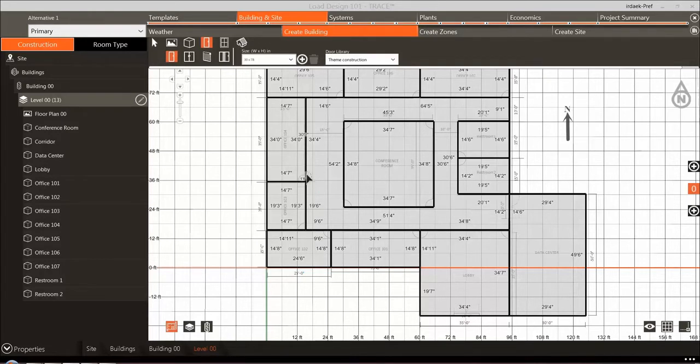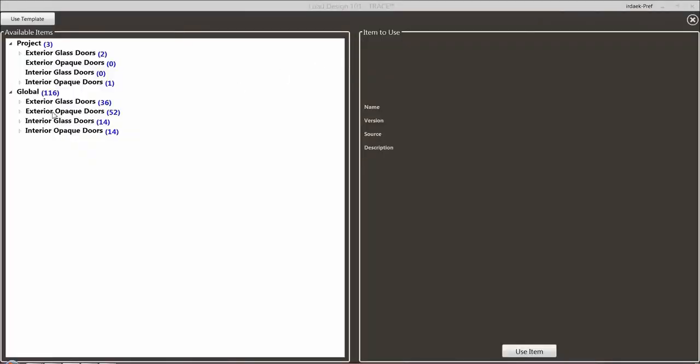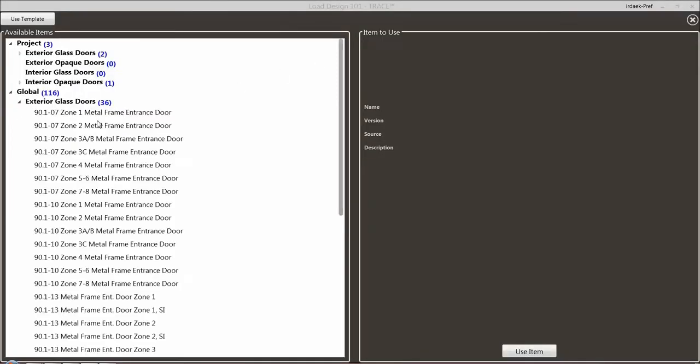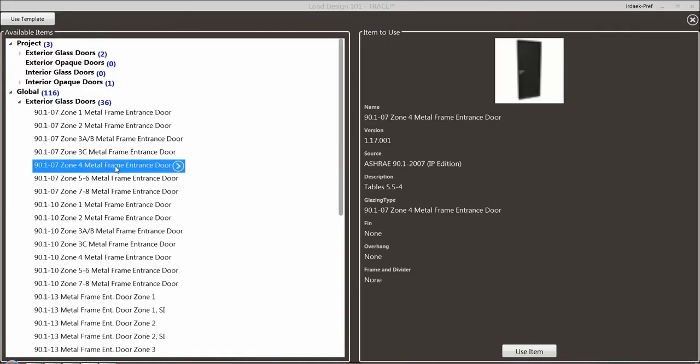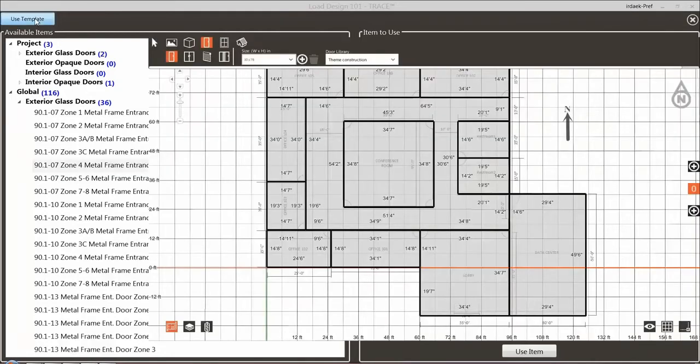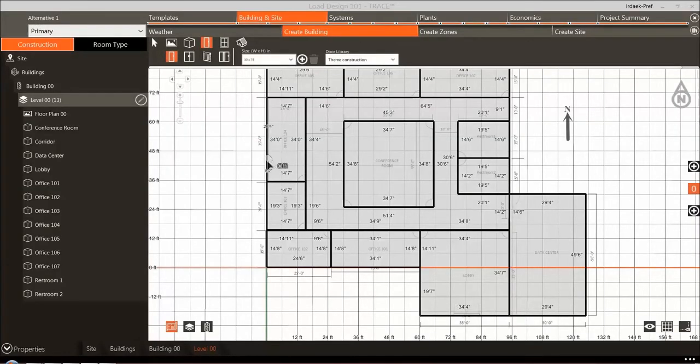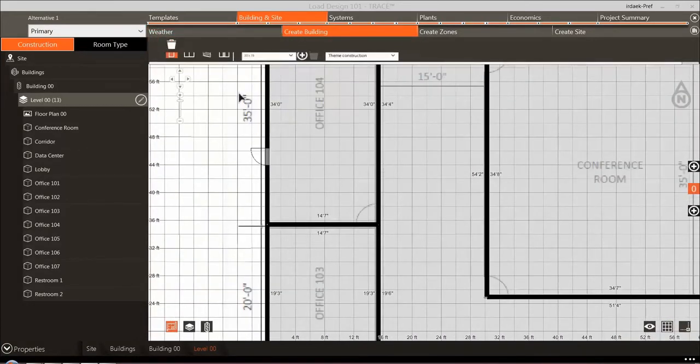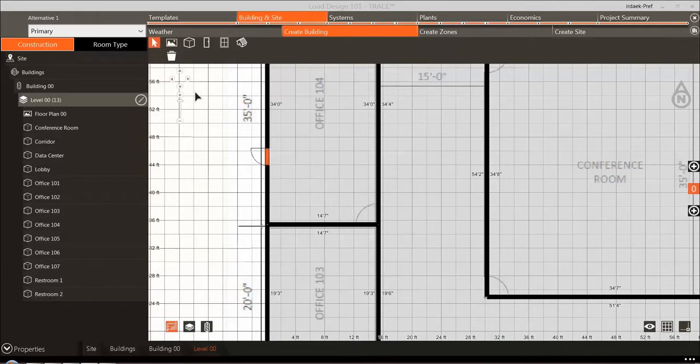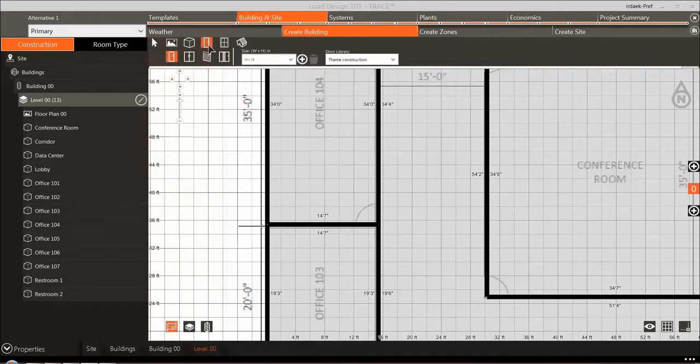The Theme Construction button allows us to switch to a different door library member instead of the one selected in the construction theme. Once the new library member has been selected from the list that appears on the left, click the right arrow button to select the desired door. To delete a specific door placed on the drawing, we need to select it from the left tree and press the Trash Can button. The Size drop-down shows typical door sizes that can be selected. The plus button next to the size changes the drop-down to dimensions of height and width.